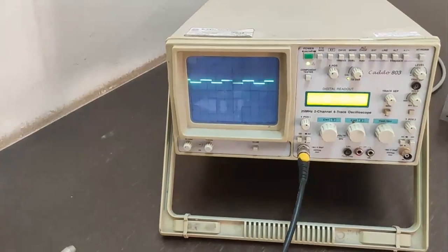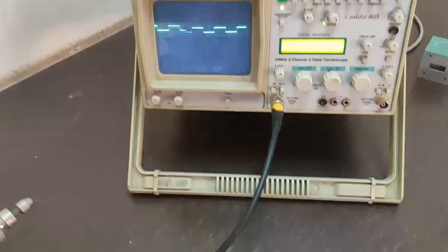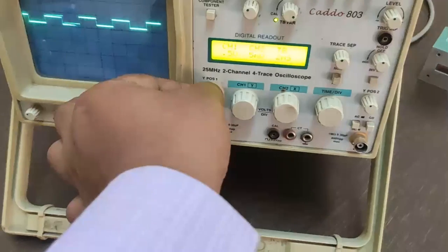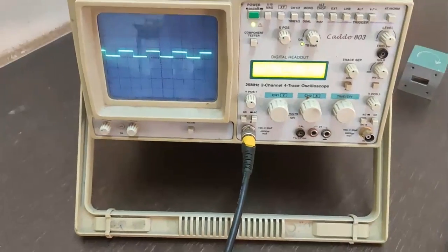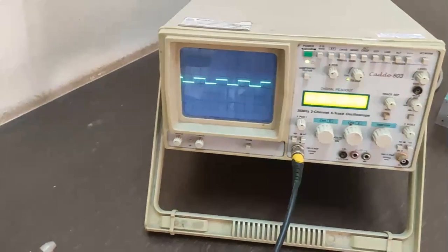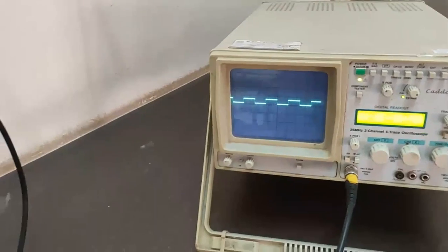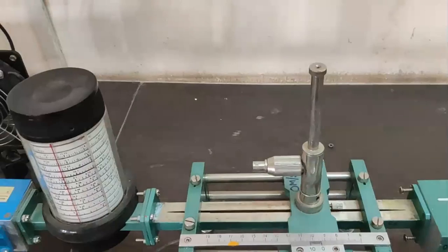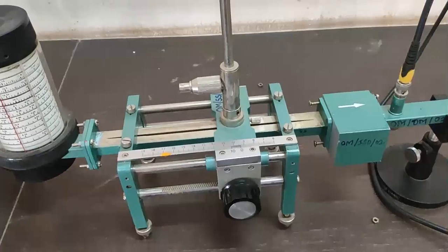After this point it starts increasing, so we go to this particular point, whose value is 0.5 multiplied by 0.5, so it is 0.25. That is the value you get for Vmax and Vmin. When you know Vmax and Vmin, you can find the VSWR easily.